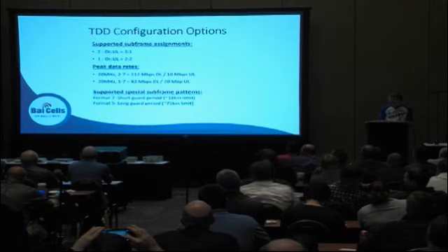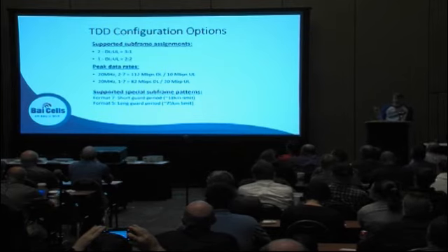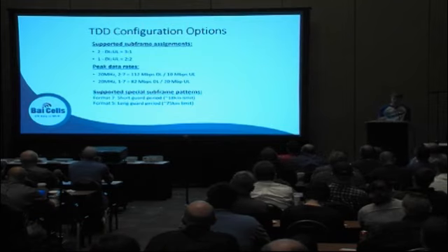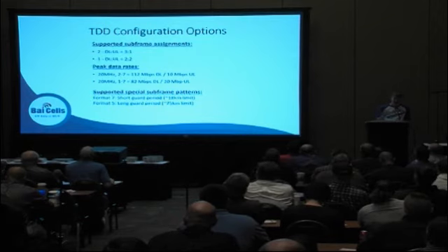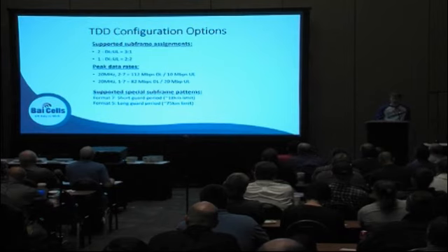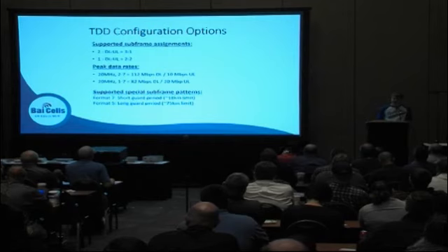Good. It's the frame ratio. This is also considering Category 4 UE, which is the category we're using. So this is assuming that the downlink uses 2 chains, 2 antennas, and that the uplink uses 1 antenna. So half the throughput is being lost because there's only 1 antenna being used on the uplink.